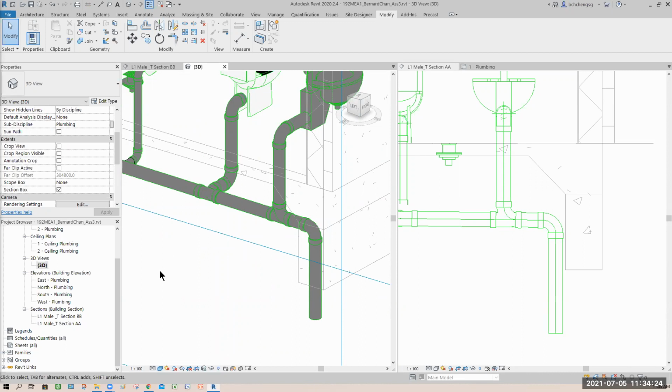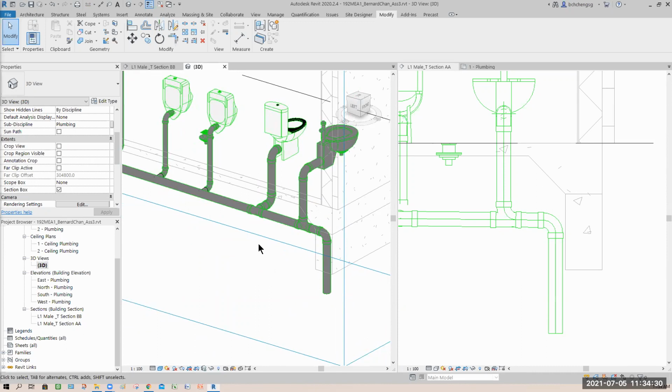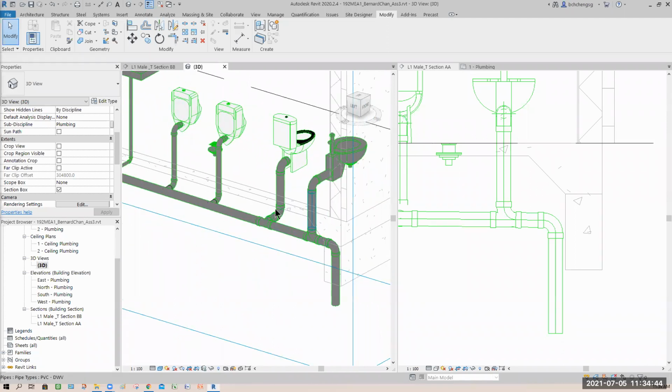In real world practice, normally, if your toilet has two pipings for the WC, and there's a connection here with fluid flowing, it's okay, you can connect this way. If not, only the first one connects to the main pipe. The second one connects directly to this pipe because they want your feces to clear fast, for the smell and the flow.